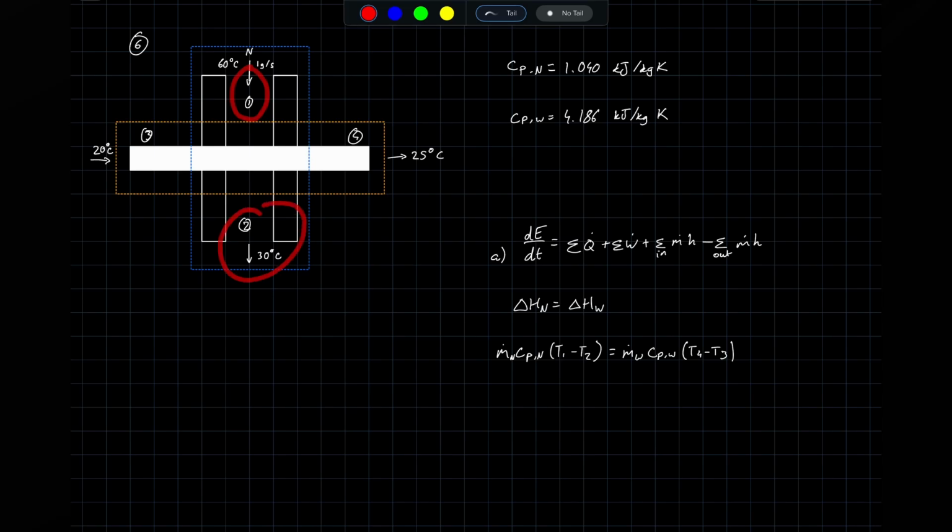And here you might be asking yourself, well, why here did you take the entering temperature minus the exit temperature, and then in this section you did the opposite, you did the exit temperature minus the entering temperature? The reason for this is that if you've got energy flowing from one system to the other, then the energy flowing into the other system is the exact same. So mathematically, it has the opposing sign. So you can imagine that this minus this has to be equal to 0.